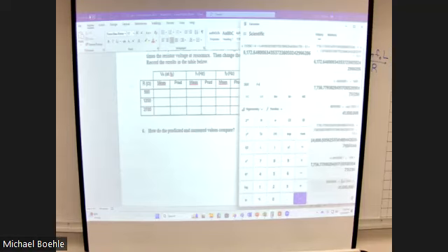So that gives me a predicted bandwidth of 6173 minus 4104, or about 2069 hertz, which gives me a predicted Q of 5032 hertz, my resonant frequency, divided by 2069, which is really close to 2.5, probably about 2.49. Remember earlier when I did the Q, I think I said it was 2.33. But that was when I used 1400 for R instead of 1300. Anyway, there you go. All right, that's all your predictions.